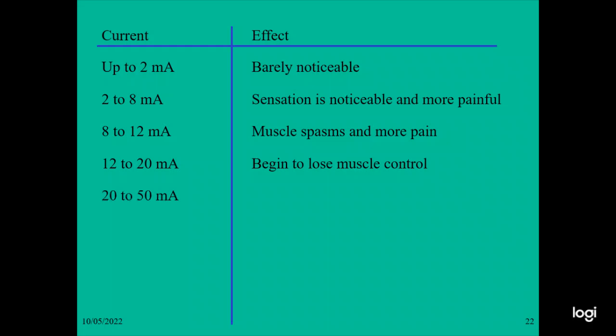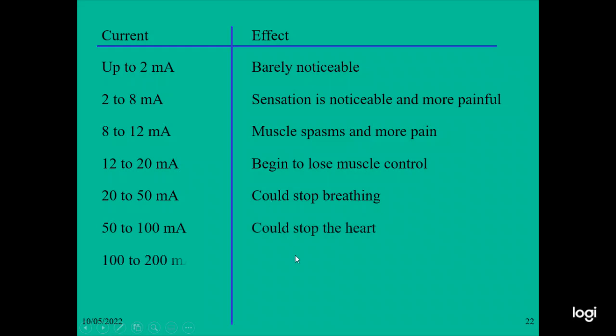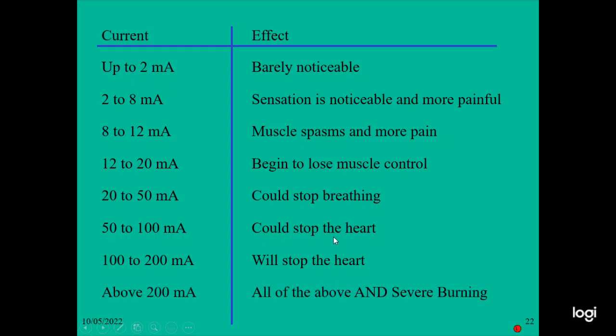20 to 50 milliamperes could stop the breathing. 50 to 100 milliamperes could stop the heart. 100 to 200 milliamperes will stop the heart. About 200 milliamperes, all the above and severe burning.